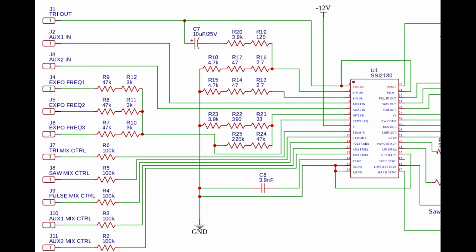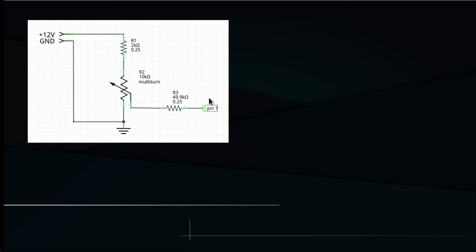It is therefore important to have a way for adjusting the bass frequency that the synth can emit by means of its exponential input. We can do that by creating a simple circuit that provides voltages in a predefined range, and those voltages can be applied to the exponential input just by adding one extra input identical to J4, J5, and J6. And here is the circuit.